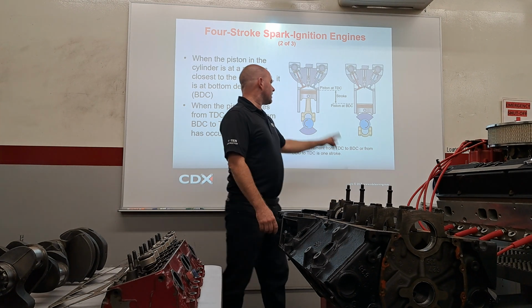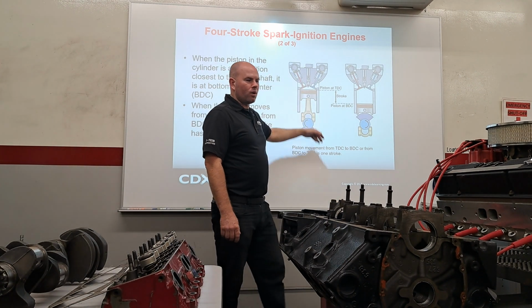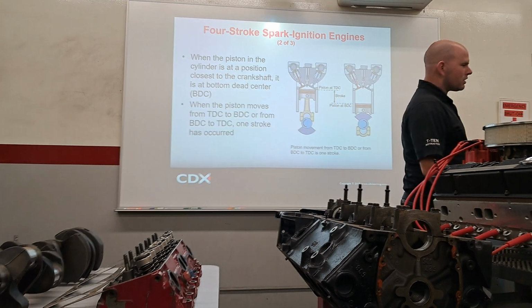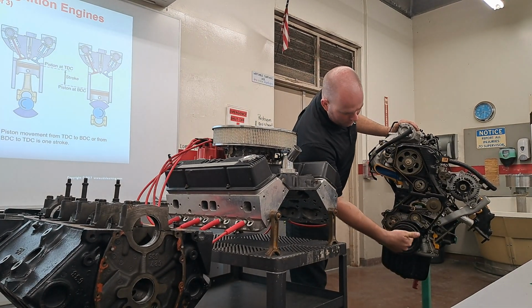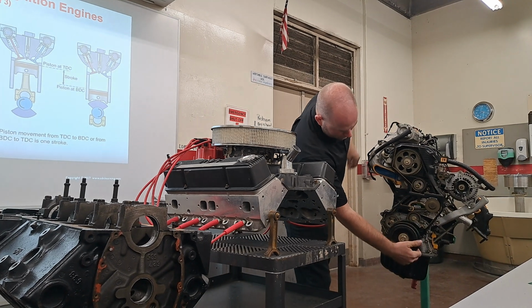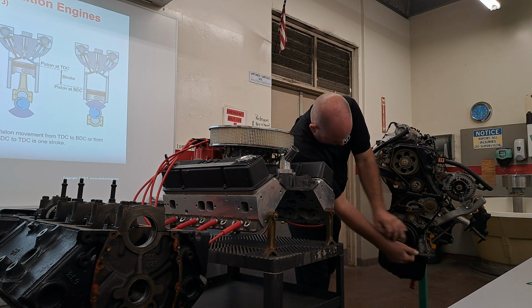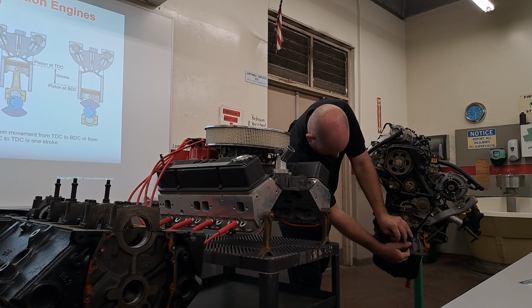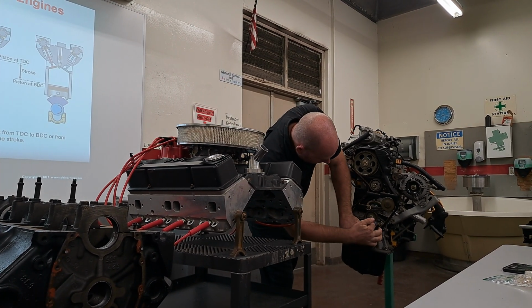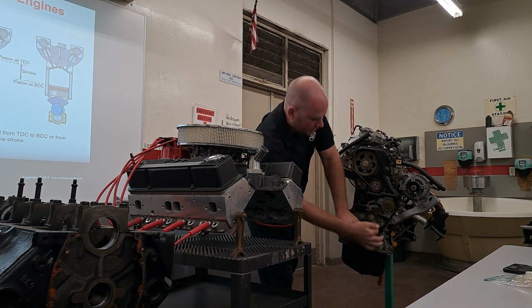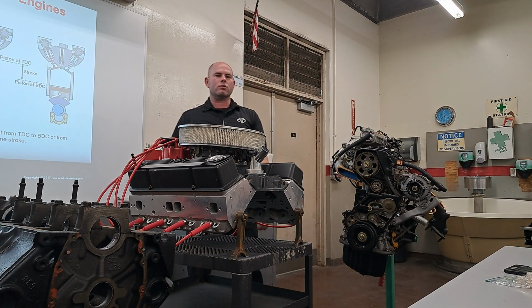That's one way. A lot of times, if you're on TDC cylinder number 1, like on this engine right here, there will be a mark on this crankshaft. Don't judge me, I'm going to get it around there. It's actually harder than it looks. There's a mark right here, and I just set this to TDC number 1. I didn't use a screwdriver, right?